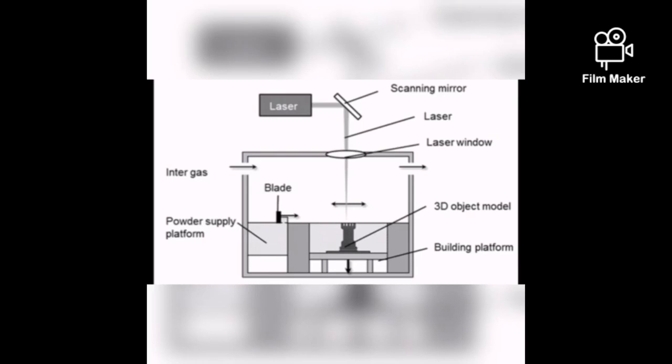put a metal powder into the supply platform. After that, the device will set the scanning speed, the laser scanning interval, and the angle. And after that, nitrogen gas or argon gas will be introduced into the device. After the appropriate volume of gas is loaded, an amount of metal powder suitable for one layer is deposited onto the base plate using a blade.